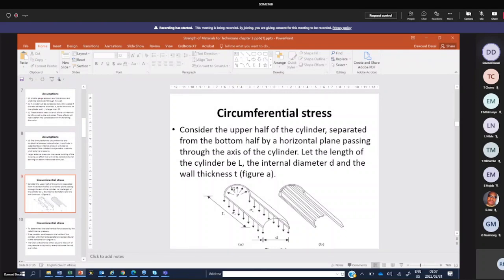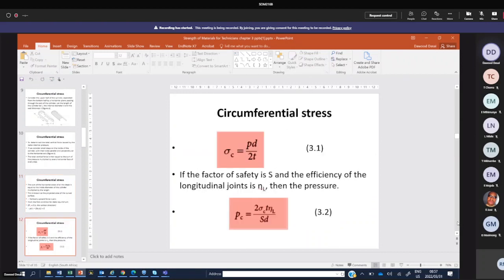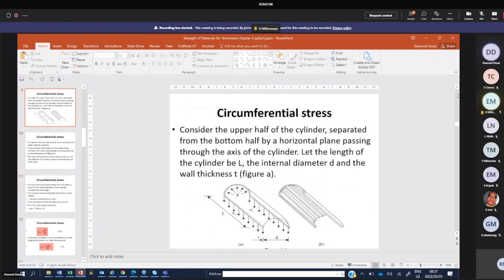That's why they're showing you in two halves. So the circumferential pressure or stress is going to cause failure in the longitudinal direction. Keep that in mind. I hope you write it down, eh? Textbooks don't explain. Then the opposite is true for your circumferential one. It's the opposite. Eh? The longitudinal stress causes rupture. Okay, let me show you a diagram here.